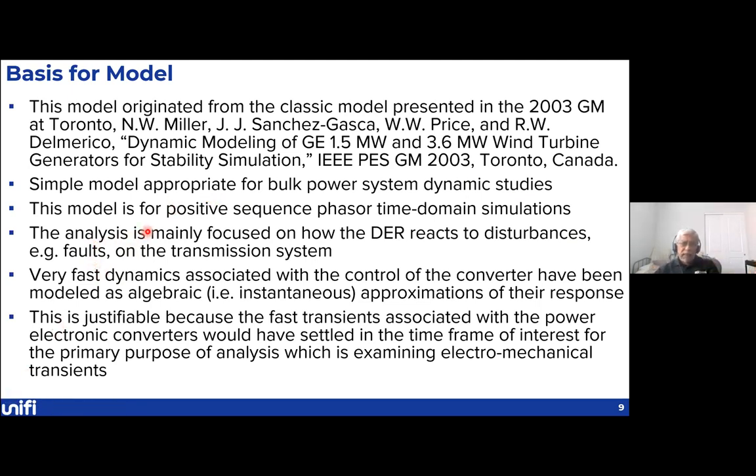As a result, in this model, the very fast dynamics associated with the control of the converter have been modeled as algebraic approximations of their response. The analytical reasoning behind this is that the fast transients associated with the power electronic devices would have settled in the time frame of interest in time domain simulations, that is, in transient stability simulations, which are primarily examining the electromechanical transients. So that was the basis for how these models were developed.